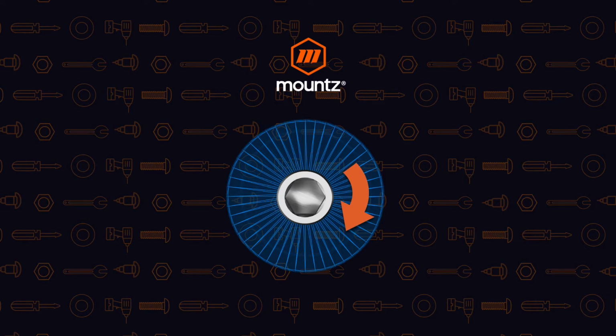For the loosen test, we would simply move the fastener and break it loose and see what that torque value is. And again, that would be a correlation to the joint characteristics, and if we are constantly seeing the same type of value, then we can conclude that the torque that we're applying here and this loosening is correct, and we are getting what we are looking for. The last one that we'll be looking at is the marking test.